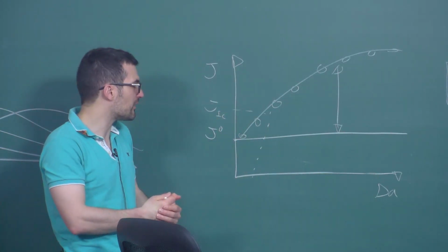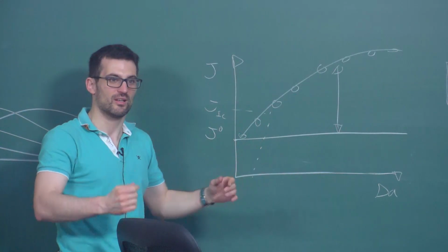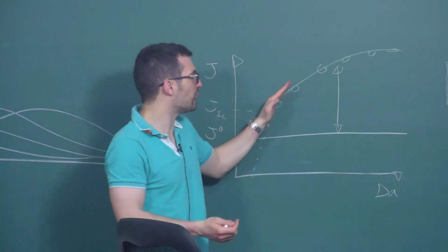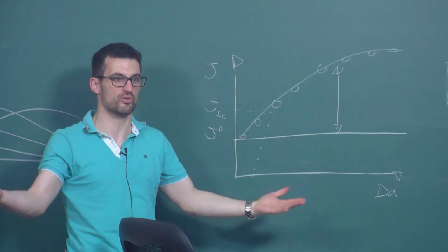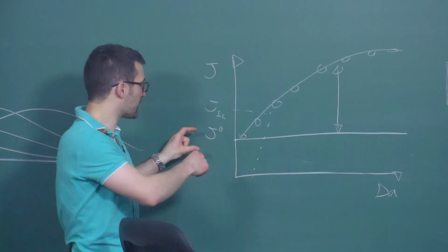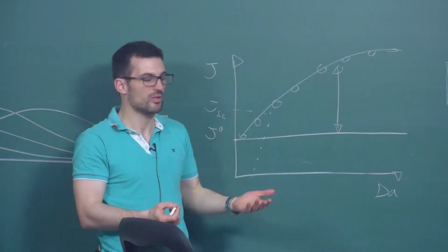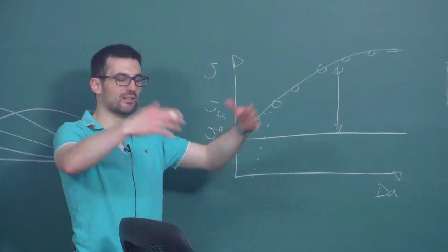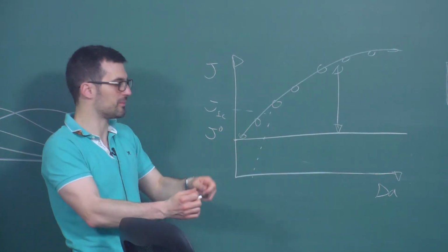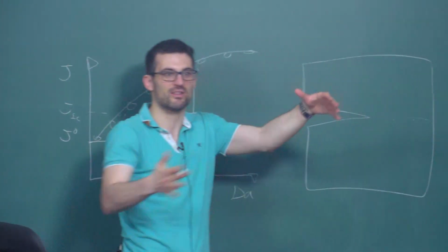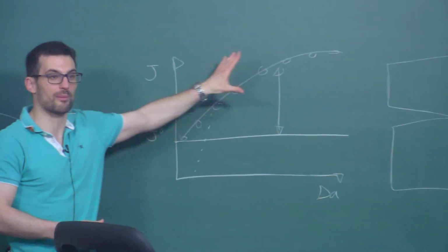So I think that it is more of an extrinsic effect in that you have a fracture energy that remains the same, but you have a toughening effect as a result of plastic dissipation. And the model will capture that. I think this is one of the beauties of the model, because how big your plastic dissipation is might not be the same in a practical component as in your fracture test, because in the practical component, maybe your plastic zone is limited by the dimensions and so on. So the model will capture that.